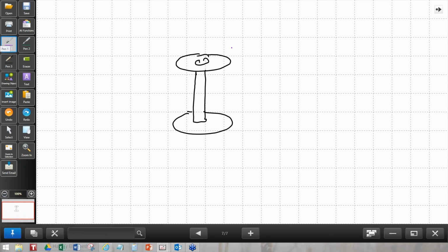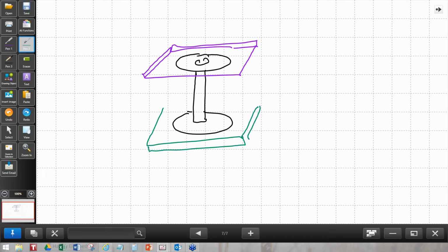Okay, another question. Does moisture get trapped if you tent both sides? The answer is yes and no, depending on how you do it. If I have a via that goes from one side to the other, and you come along and tent it over this side with something, and I'm going to come along and tent it over the other side, the hole is now as if it's like dry film.